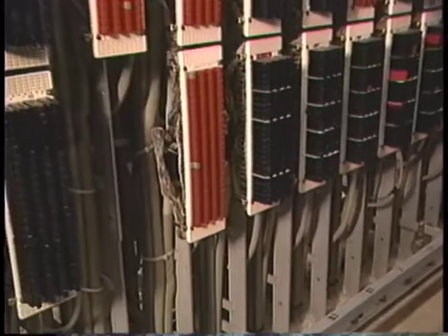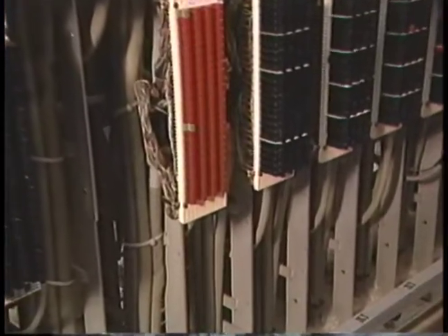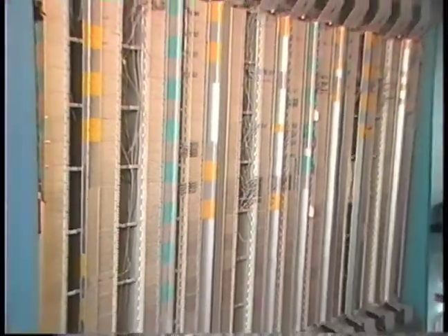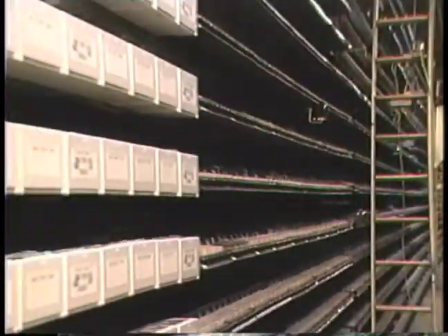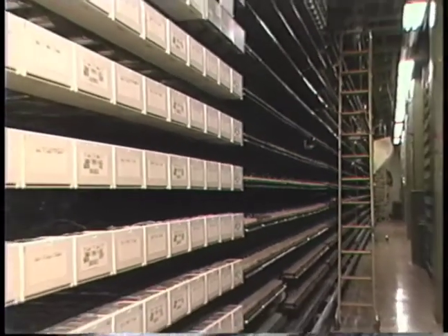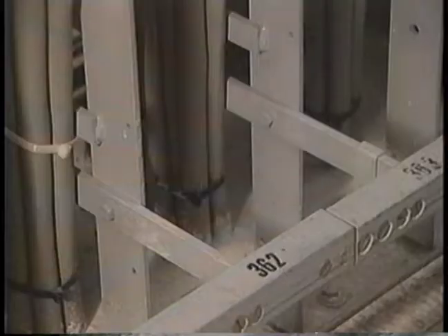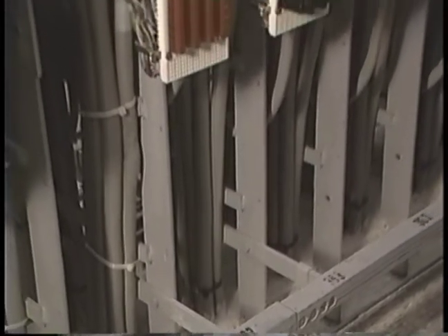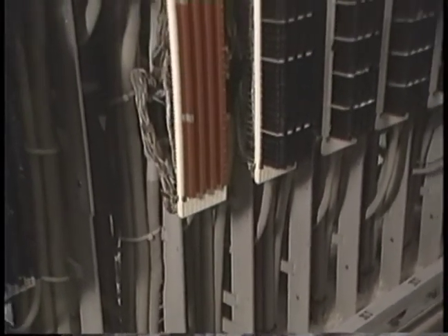Trunk cables from other offices also connect to the MDF. The trunk distributing frame connects trunk switch frames to trunk circuits. Generally, both line and trunk cables terminate on the MDF. Cables that contain lines from the cable entrance facility are routed up through different floors to the switching and transmission equipment. They're called riser cables.